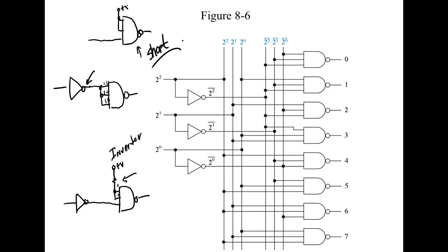We had a disk drive where the power supply kept kicking out. We call it a crowbar circuit. Most well-designed power supplies will shut themselves down if they sense overcurrent, and that prevents the power supply from burning up stuff. So we had a disk drive, back when disk drives used to be used, that kept crowbarring the power supply.